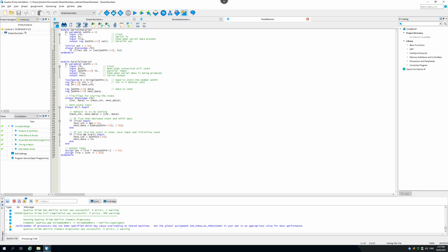And here's our shift register right here. Our shift register will start off with the number we wish to send. We actually see that in here, and I'll come to that in a second. Every time through, we first send bit 24, then bit 23, then bit 22.